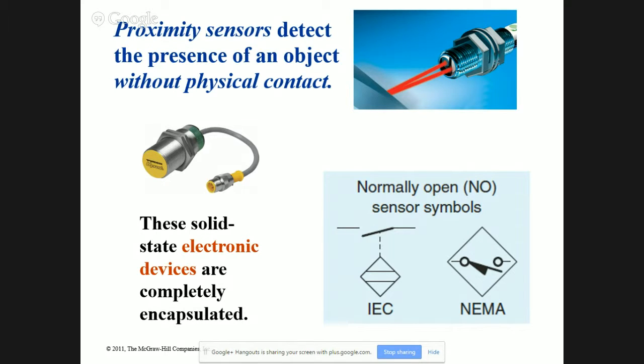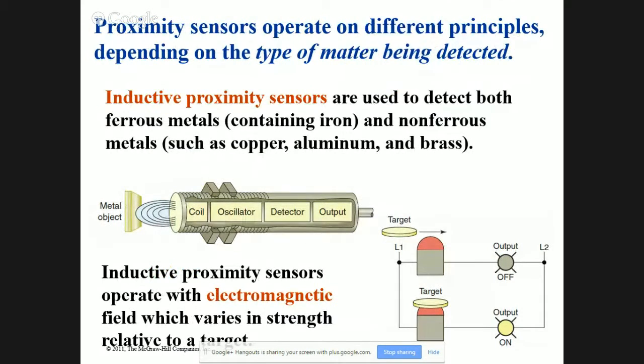The same thing goes for a photo eye. This photo eye has little rays coming in. But here's how a proximity sensor works. It puts out a little field. You can get proximity buttons to replace pushbuttons. We used to put them on machines. The buttons would get cycled maybe 5,000 or 6,000 times a night. Well, that doesn't last long for a button.